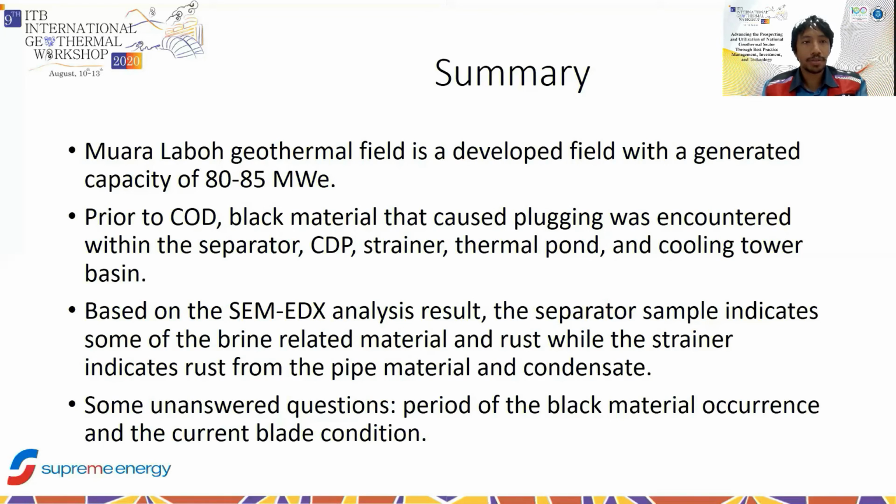Based on the analysis result, it was mostly iron sulfide or pyrite. And the reaction between inner pipe and also the condensate created that material. There are also 2 questions left, cannot be answered now, because of the period of black material occurrence.